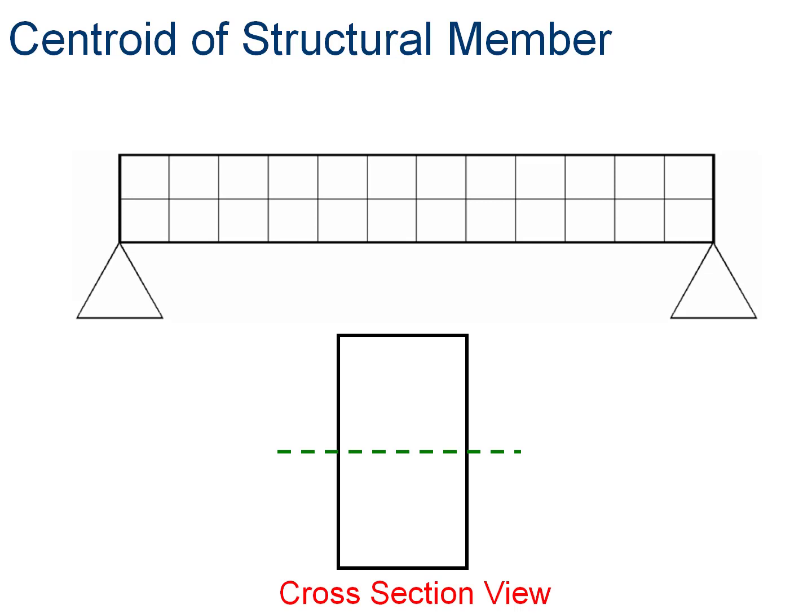I'm only showing you the centroid in Y because we're going to apply a load to the top of it. So where the centroid is located right here, this is referred to as the neutral plane. That is the neutral plane. And it's the axis of symmetry that the centroid lies on.